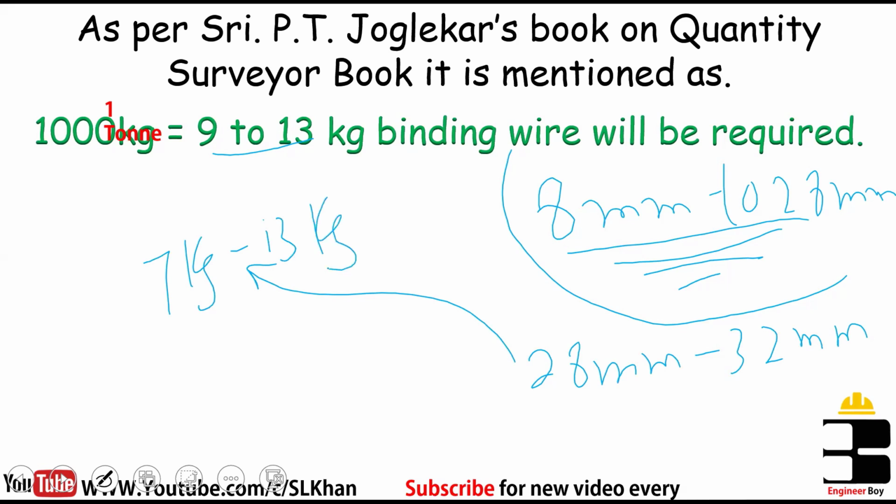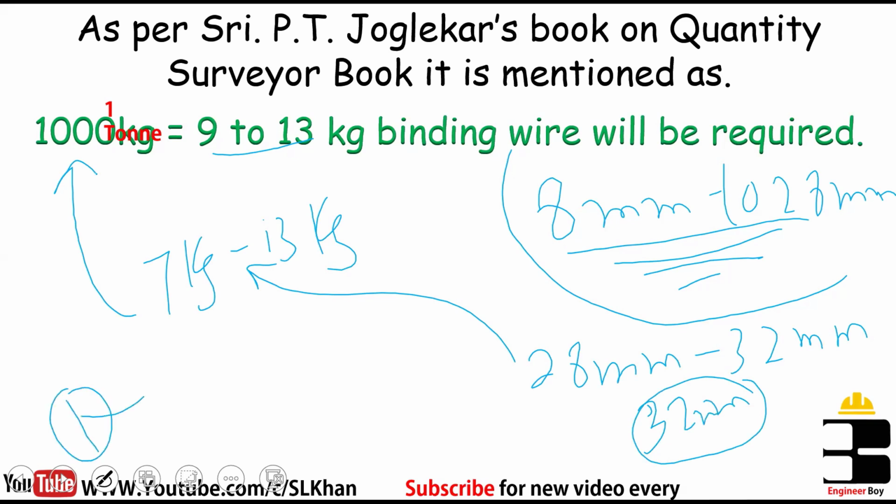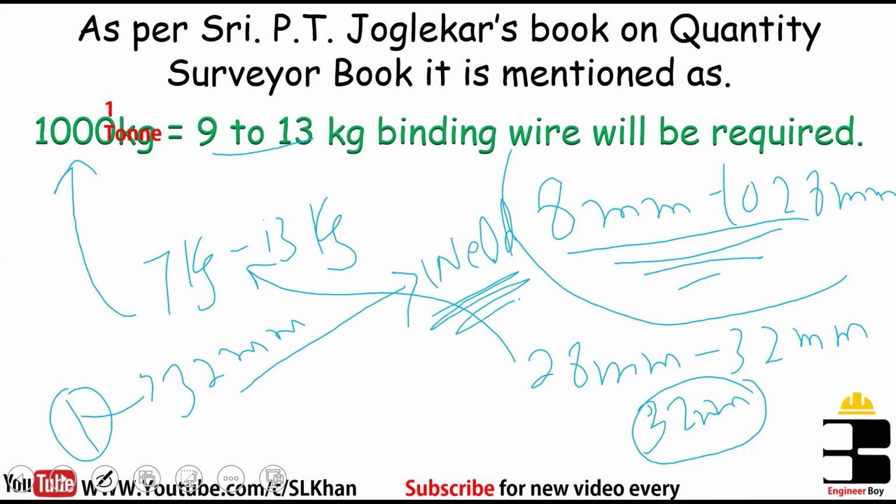And for how much work? For 1000 kg of work. So this is just the basic concept. Now what if the diameter of the bars is increasing, more than 32 mm? Then there is no need to bind the reinforcement. Instead, there can be a requirement of welding.